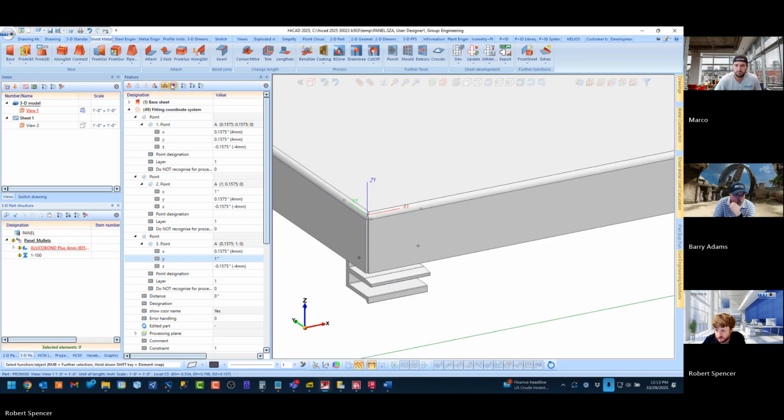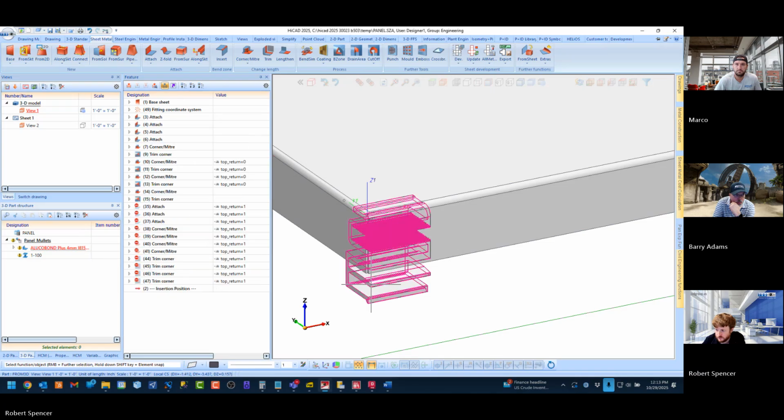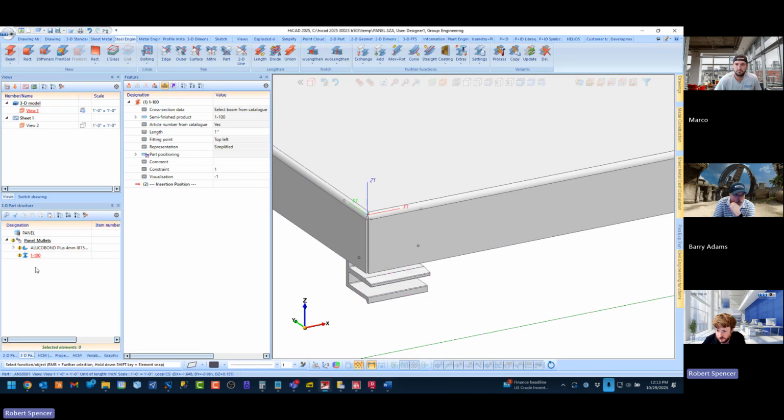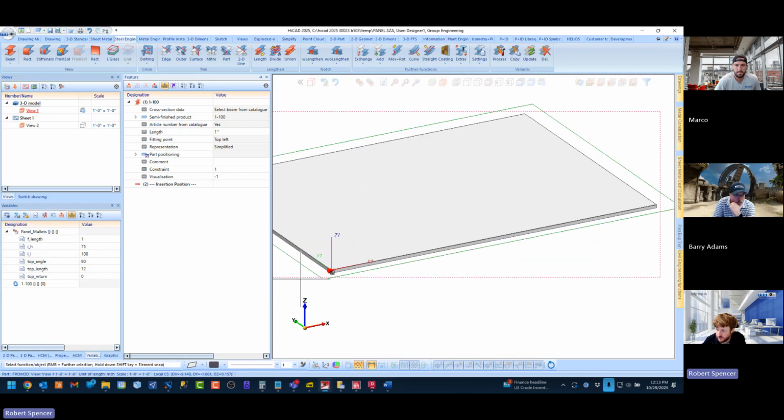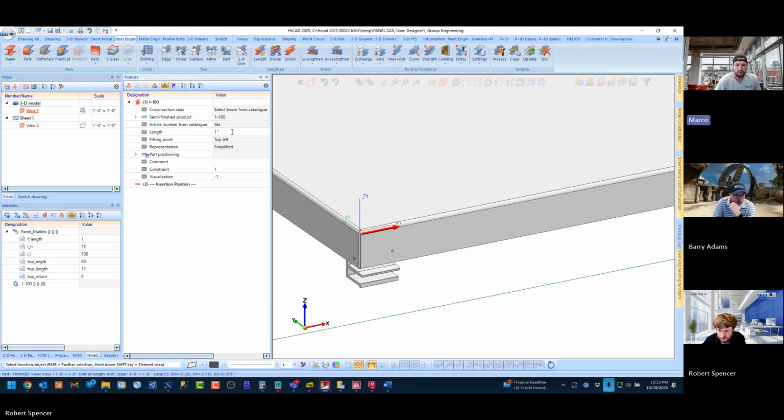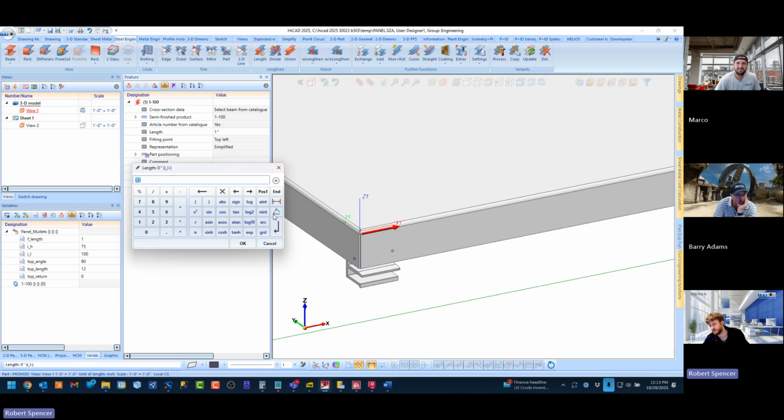So now this thing's looking a little short. Well, here's the length. What value do we already have that exists that we could relate very easily to the length of this panel? IL. IL. I of L, and to make it exact, we then want to say minus 4 millimeters times 2, so that you got 4 on this side, the thickness of this flange, and 4 on the other side. So if I say minus 8,